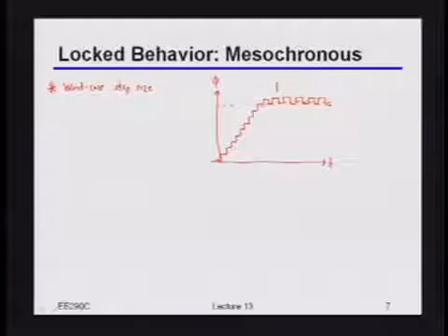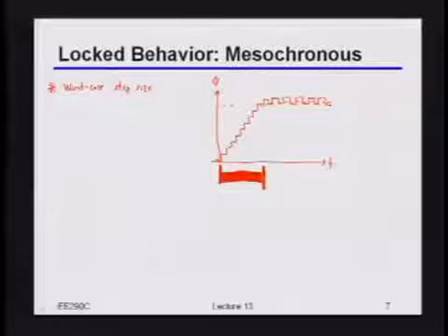But yeah. Time taken to lock? Ah, okay, so you may indeed care about how long it takes you to lock. That is indeed true. Although, if I'm in a mesosynchronous system, usually I can tolerate a pretty reasonable amount of time. Because in a mesosynchronous system, things are nominally at the same frequency, but I just don't exactly know what the initial phases were. So once I find that, it's a matter of catching drift types of mechanisms, right? Given that, what do you think you're going to want to do to that step size? So you're really only looking for drift.